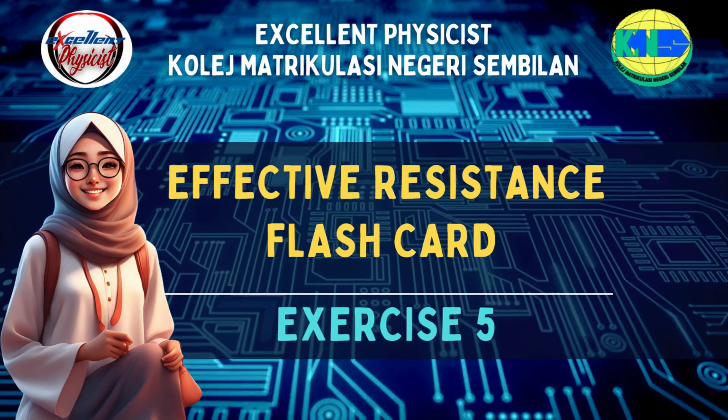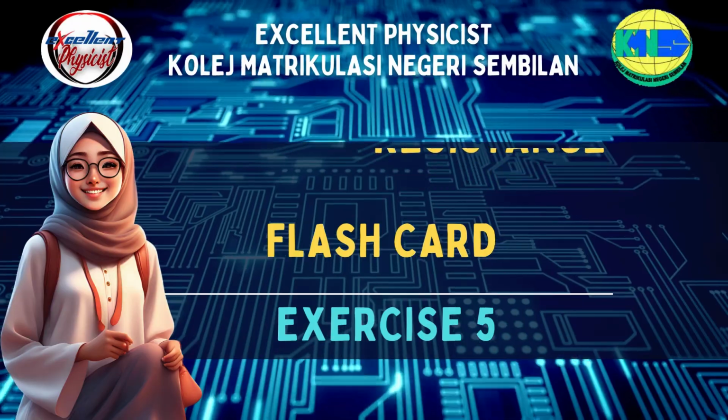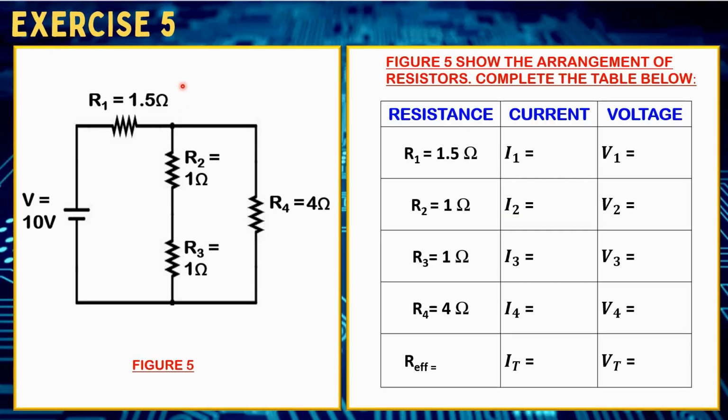In this video, I will discuss the exercise that relates to the effective resistance. Exercise 5. Figure 5 shows the arrangement of a few resistors in a circuit. From the circuit, we know that V total is equal to 10 volt, R1 is equal to 1.5 ohm, R2 is 1 ohm, R3 is 1 ohm, and R4 is 4 ohm.